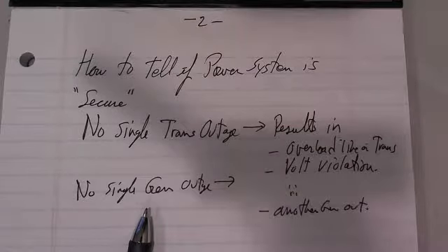Certainly Puerto Rico does not have any connections to anywhere else. It's too far distant. And therefore, if they lose a generator, they really better have extra generators online, or they better have the ability to shed load very quickly.